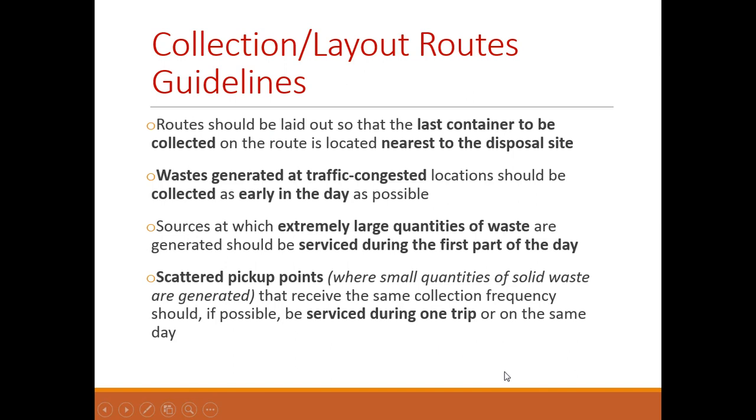Additionally, your routes should be laid out so that the last container to be collected on your route is located nearest to the disposal site. In other words, you start furthest away from the disposal site and end nearest to the disposal site, for example, if your disposal site is a landfill.